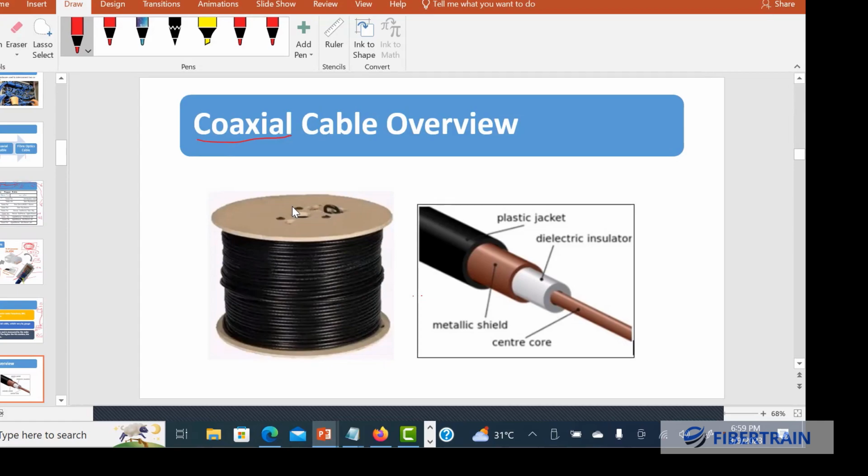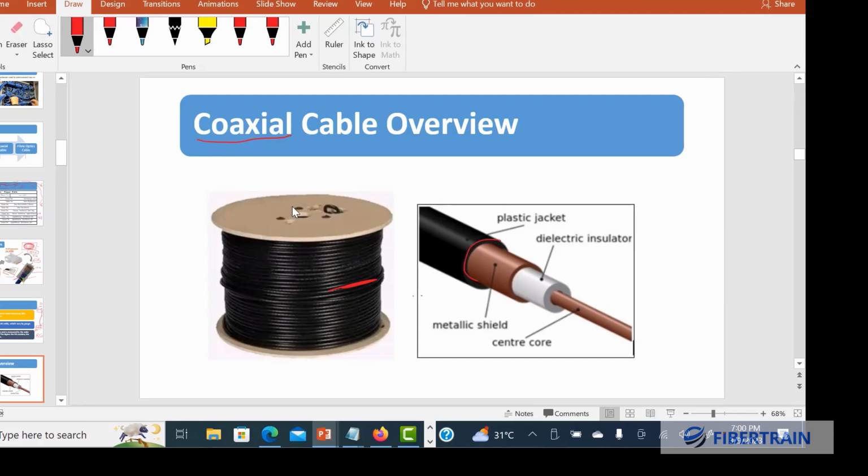When you take one of these coaxial cables that you are seeing here, if you unroll it and bring one out, it looks like this. You have to cut out the outer covering, which is the black. You see another inner covering. You have to remove this other one. You see another inner covering, which is like silver. You have to remove it before you see the actual cable. This is the actual cable, the core.